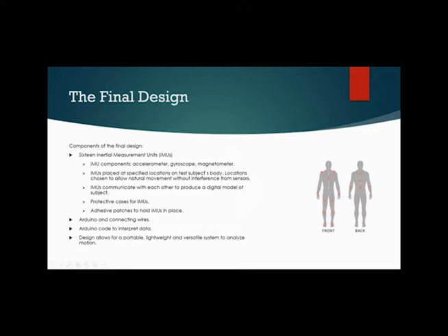IMUs are secured with adhesive and bands in positions that don't restrict movement or interfere with data collection. The IMUs communicate and are coded with Arduino. Arduino has open source libraries for IMU data collection such as this. It will collect the desired data needed to compute data such as forces and torques on the skeletal structure. The final design was to be lightweight and easy to use for all demographics.